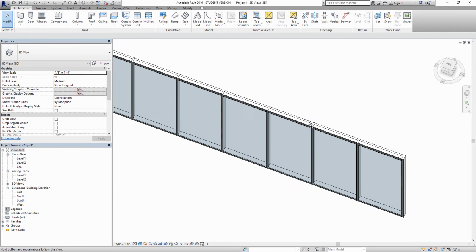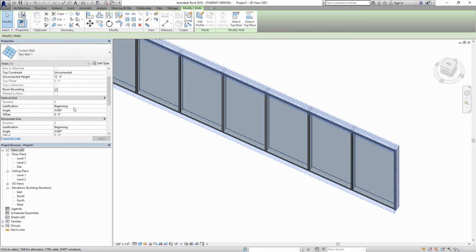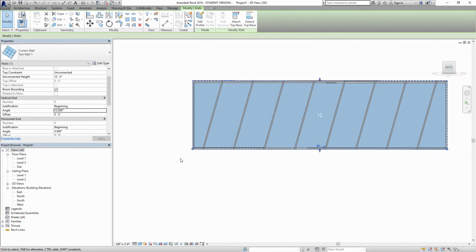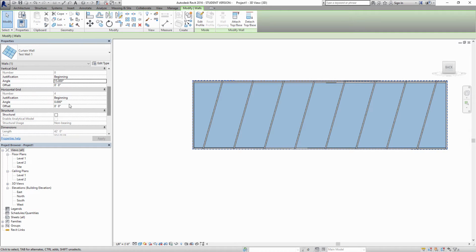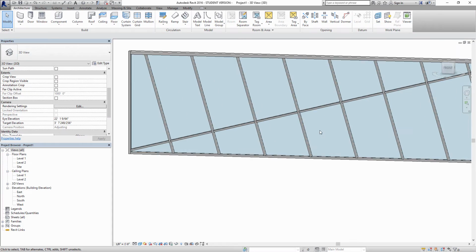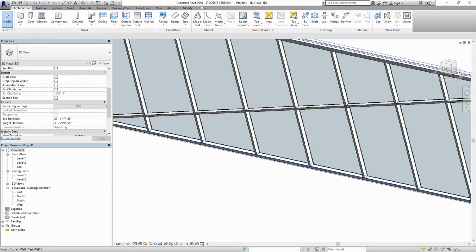The next thing I want to look at is just a couple options on how to place those mullions. I can see down here that if I wanted to, I could slant them at, say, 15 degrees. We could have kind of a strange mullion layout that way. I wonder, I've never actually done a horizontal grid. There you go. You can actually keep these things perpendicular by making our horizontal bent too. Just an option.